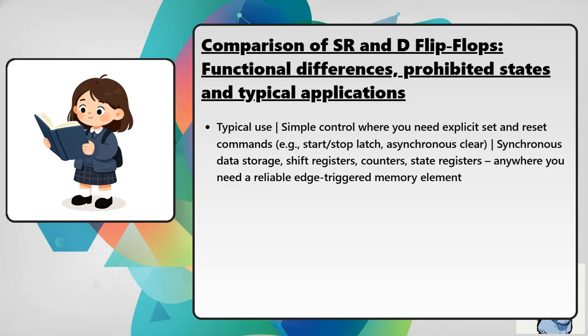Typical use: simple control where you need explicit set and reset commands, for example start-stop latch, asynchronous clear, versus synchronous data storage, shift registers, counters, state registers, anywhere you need a reliable edge-triggered memory element.